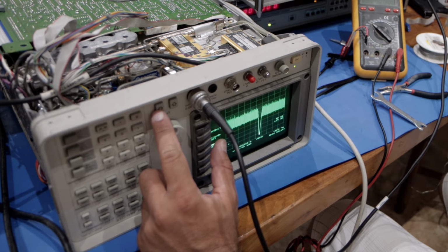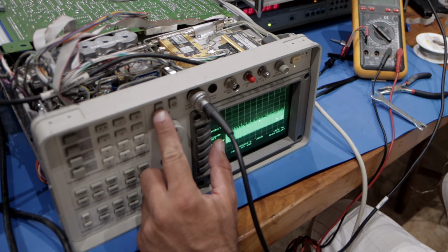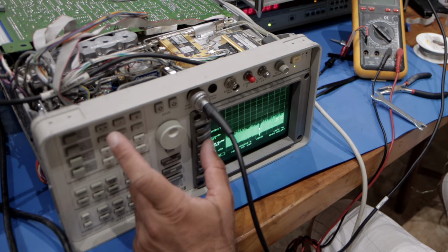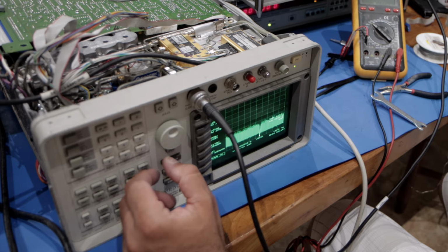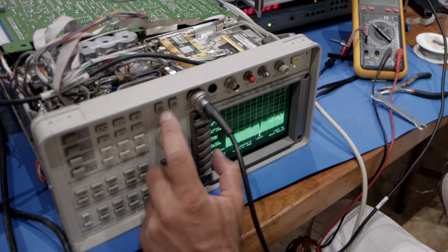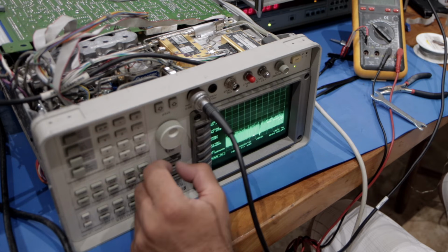Right now, only the 20 dB, 40 dB and 60 dB settings give a reasonable power reading, though not the correct one. But every time the 10 dB step is involved, the signal gets much weaker. That's definitely not right. So I need to open the attenuator's RF cover and inspect those resistor pads closely. Looks like this attenuator was a complete loss after all. But yeah, this one is on me. It was a gamble and I lost this round.